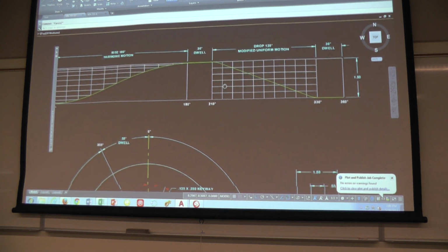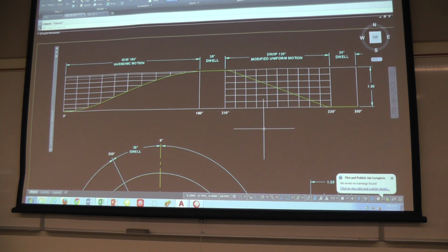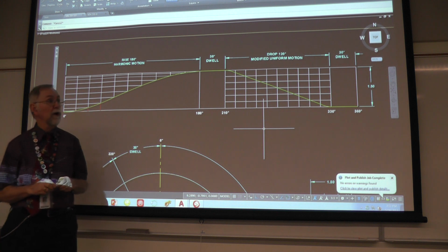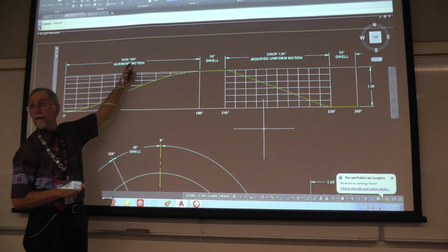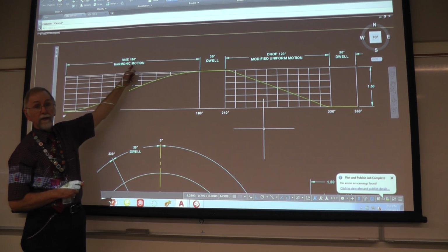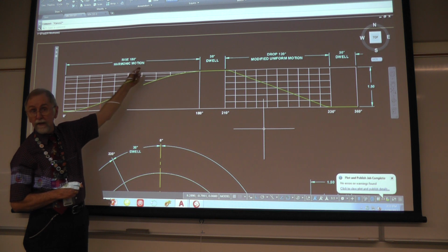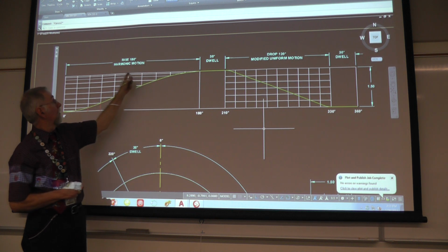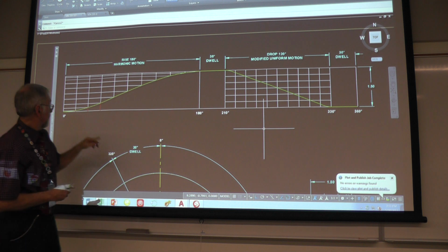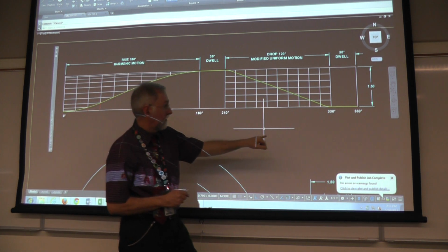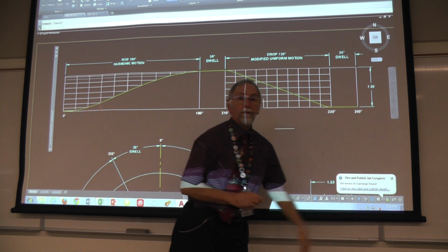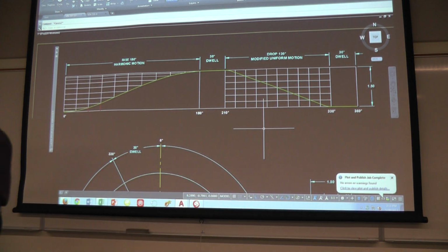Just so that you realize that's what's going on. And then just like you did with the CAM displacement diagram project assignment number 9, you're going to add in a linear dimension and override the text in here to get rise 180 degrees, using %%D for the degree symbol. Harmonic motion. Label 0 degrees, 180, 210, 330, and 360. All right.